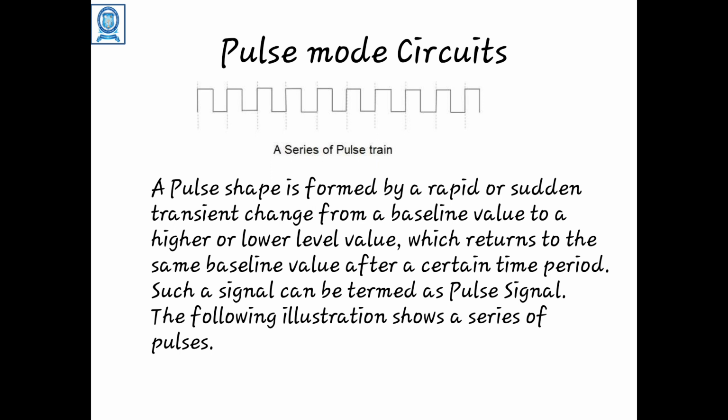There are n input variables, m output variables and k internal states in this type of circuit. The delay elements provide short term memory for the asynchronous sequential circuits. These are called secondary variables and excitation variables.